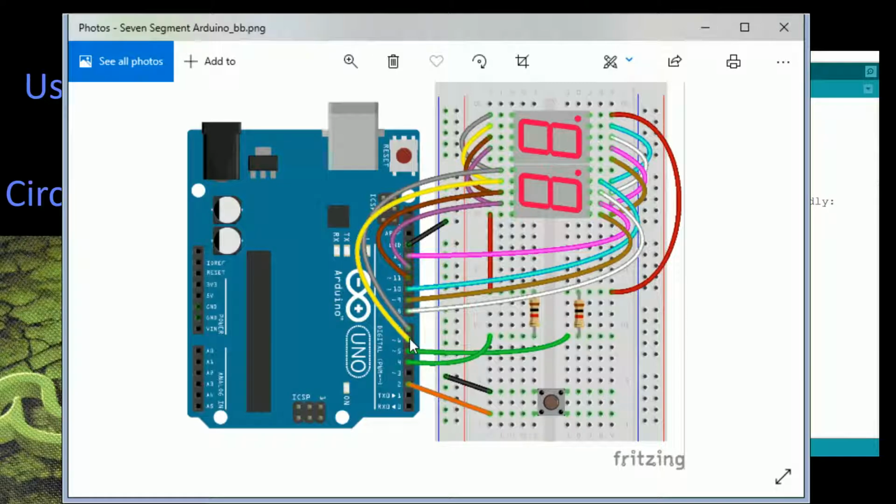In fact, let's follow the yellow wire, because the yellow wire is connected to pin 6, which happens to be the A segment. So it comes up to here, it makes contact here at this point, and then jumpers over to the same spot, A, on the other one. What changes is this pin that's on the end here. So what we have here is a pin, and this is for pin 1. This is all on one chip. So what happens is, this is telling me it's the left-hand segment. This pin way down in this corner is the right-hand segment.